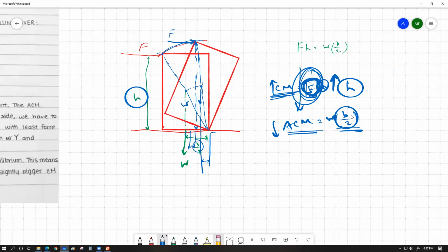Which means that slowly the anti-clockwise moment that we have to overcome becomes lowered, and the perpendicular height through which we can apply the force F is becoming more, which means the F would become smaller. That's the key point. Sir, will it be important when it comes to MCQ questions? No. This is a concept that you need to understand.